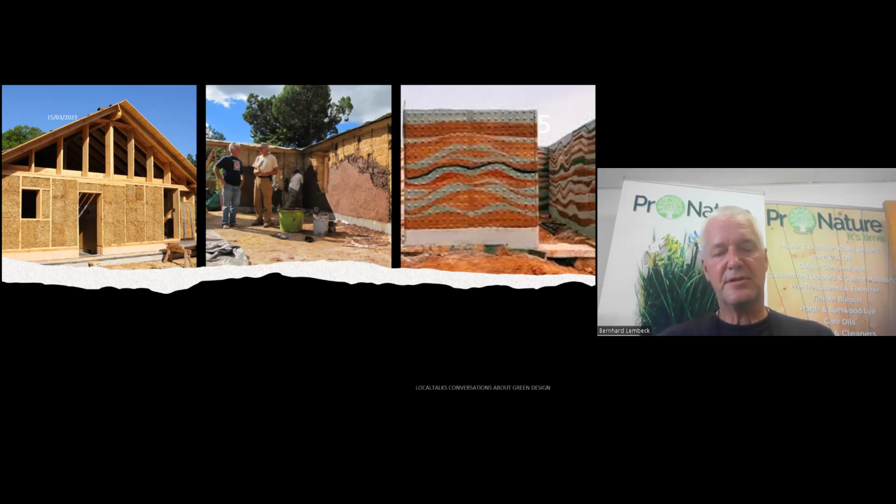Breathable coatings in general are suitable to release moisture from moist substrates, which will protect the substrate, but main moisture removal cannot be through the actual coating, but through proper ventilation. I think that is very often overlooked. So what are these breathable coatings?